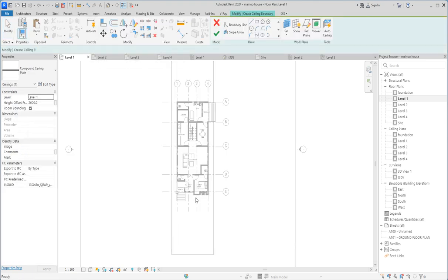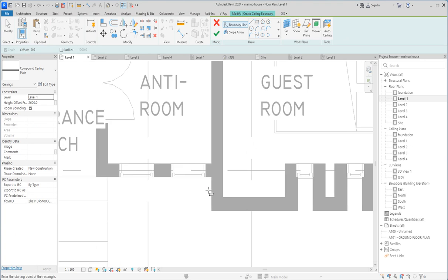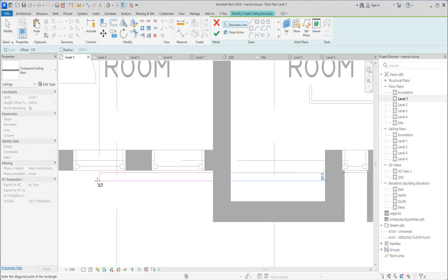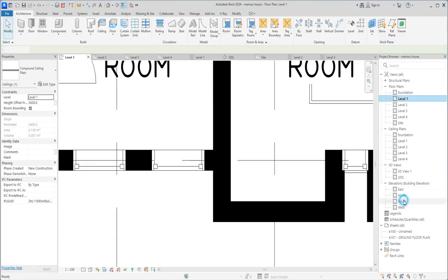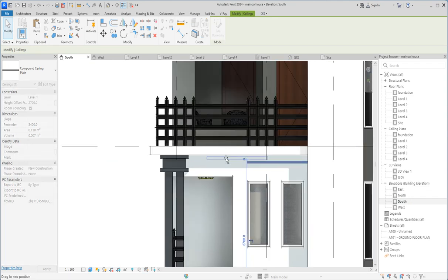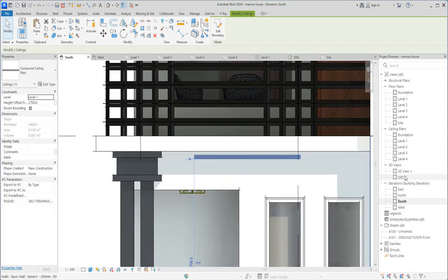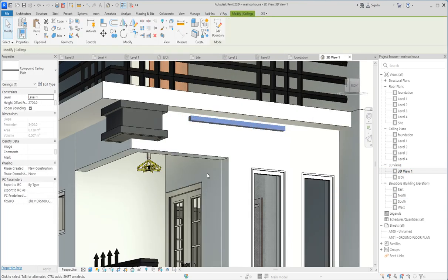So I'm going to draw a sketch for the ceiling. At this point, this is what I do by just using the rectangle. So I'm doing this one here. So click finish, go to front elevation. Do I still have what I need to have for now? I'll adjust this one and bring it here. So check it in your perspective. It is absolutely okay. Yes, so you can just move it and say 3000.